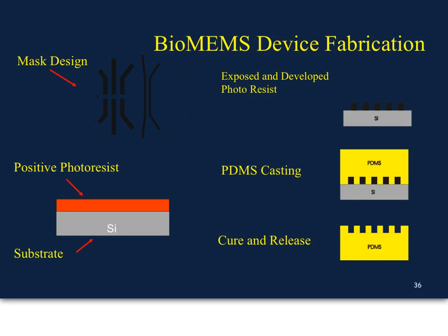So here's the idea: you take maybe a slab of silicon, you expose and develop your photoresist in the pattern of channels that you want. Then you cast your PDMS on top of those channels. Then you cure and peel off the PDMS, and then you've got your channels in the pattern that you want them.